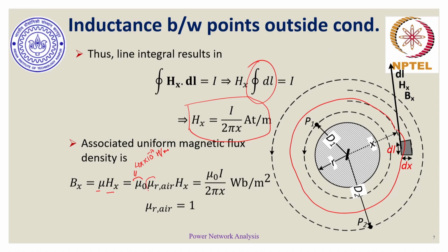And the relative permeability of air is also considered, where air is a very bad conductor, not only from electrical perspective but also from magnetic perspective. So, mu r of air is equal to 1. It's as good as the conductor being considered in a vacuum space outside the conductor. So, B of x we can also find from the expression of H of x.